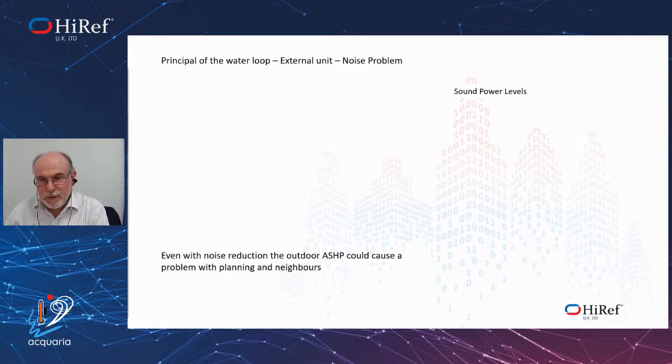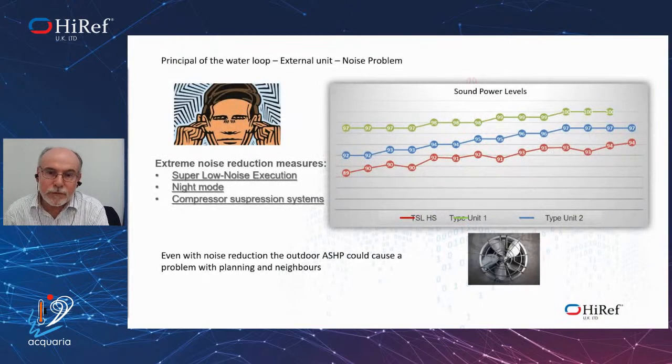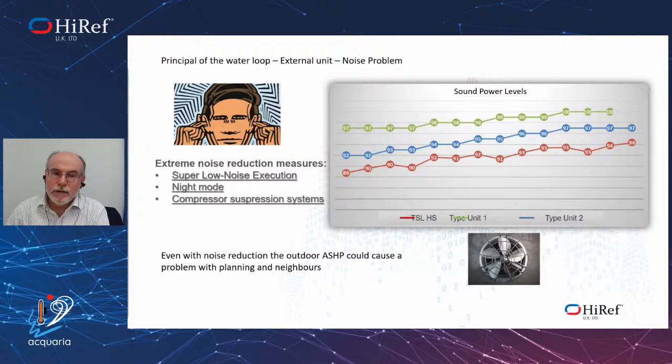Now, the problem is that when you've got units outside, you've of course got noise problems. The noise is generated from the compressors as well as from the fans. When you had a dry cooler, it was just the fan noise. But of course, once you put the compressors into a heat pump, then you have to think about how much noise is external.